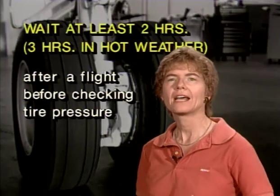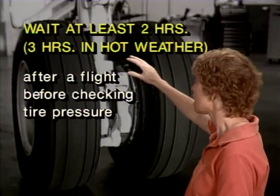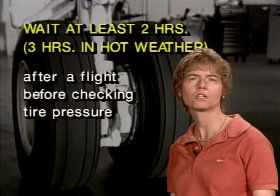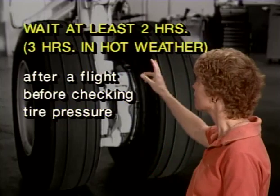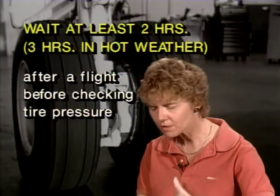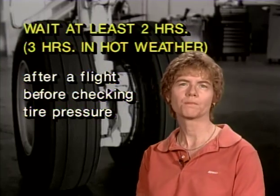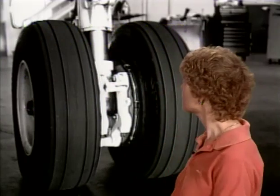Now, how long should you wait after a flight before you check the tire pressure? At least 2 hours normally, but 3 hours in hot weather. Wait at least 2 hours, but 3 hours in hot weather after a flight before you check the tire pressure. Give them a chance to cool off and get down to their normal pressure. Now, assume that you're checking the pressure in tires that are mounted as duals.